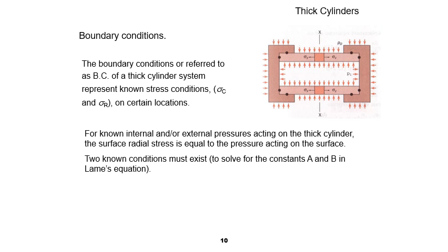Boundary conditions, as I mentioned before, we have two earlier due to atmospheric pressure and internal pressure. Right. So that is in this paragraph here. So knowing those two, then we can solve for A and B. So if you have a closed end, outside is all Po and inside are all Pi. And again, P will create the radial stress.